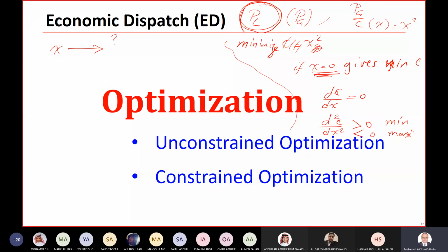The power system operator, in order to keep the system stable, may interfere and switch off some loads. This is what we call load shedding, but this is in a critical situation. It is not implemented regularly, but in critical states. But generally speaking, we are talking about a steady state problem. By the way, the economic dispatch is a steady state problem.